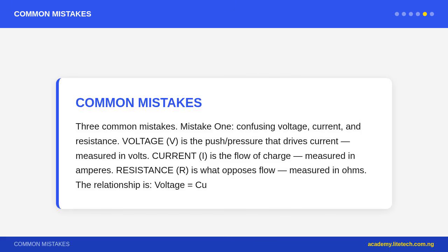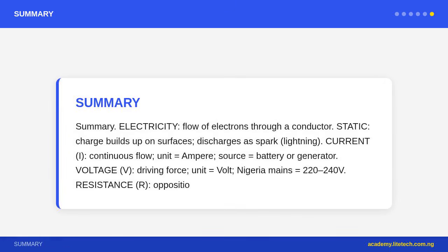Mistake 3. Drawing an open circuit and saying current flows. Current only flows in a closed, complete circuit. If the switch is open, or a wire is broken, or a component has failed, the circuit is broken and no current flows anywhere in the circuit, in a series circuit.